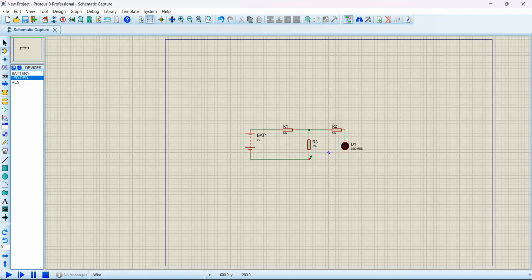Then I'll come to this junction, double click. Remember, I can't make this wire diagonal to the LED. I want my circuit to be neat. So I'll go, and then once I get here, I will have to double click so that the wire will be bended.